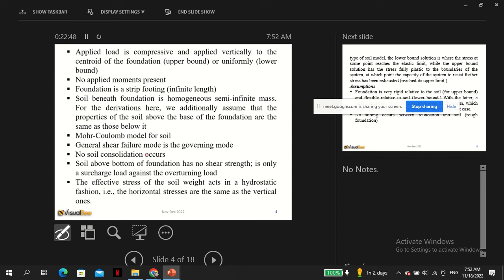Compaction is densification of soil by removing air, and we remove air by using loads and some vibration action. Consolidation is densification, yes, but by removing water specifically, and of course water is removed by such as the vibration actions cannot affect water. So consolidation is basically densification